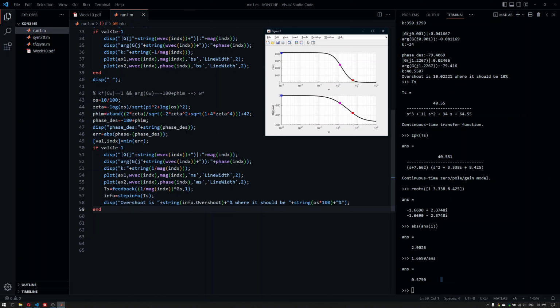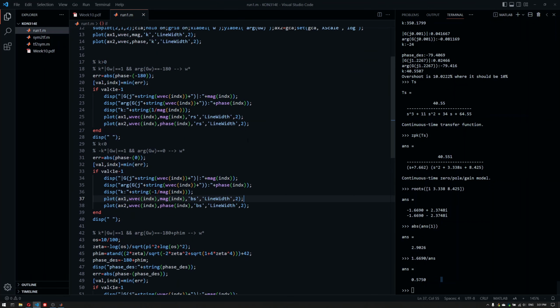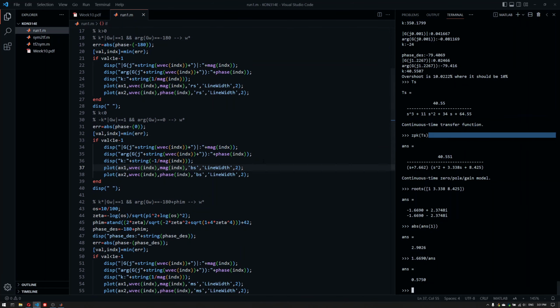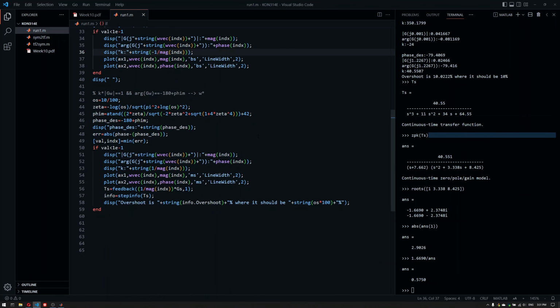Now, in terms of exams, when you're asked to do something like this in an exam, just do it once. Don't improve on it if it's not needed. Or you might ask whether you need to improve it or not. Because if there's nothing clear, most of the time the initial solution is needed here. Because you don't have MATLAB in exams, you cannot check if it's the valid one or not. So you just need to use a phase margin of 40 and be happy with it. If, for example, you can look for time domain verification, you can then maybe conclude somehow that it will not function well, or it will, based on the pole zero map of this.